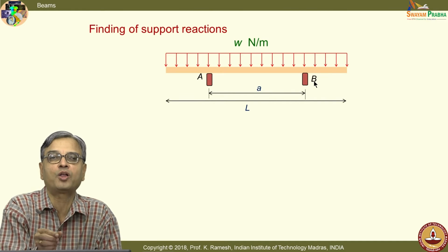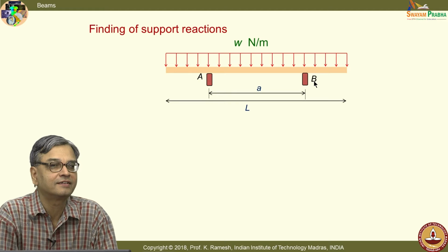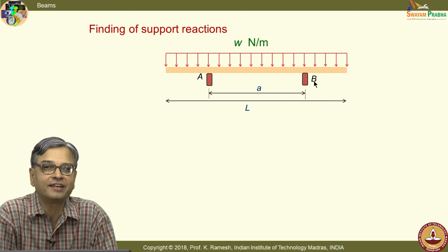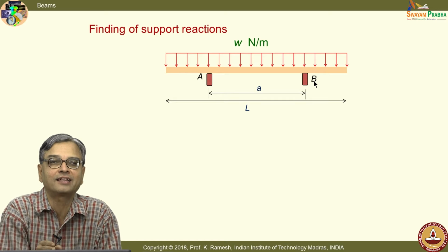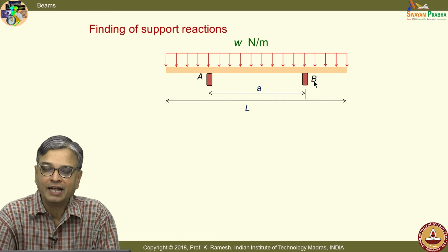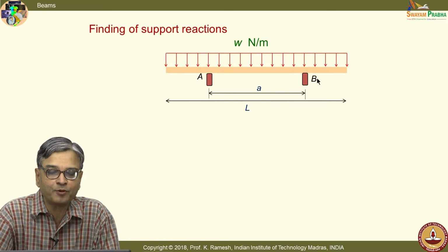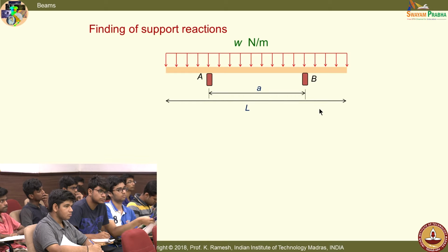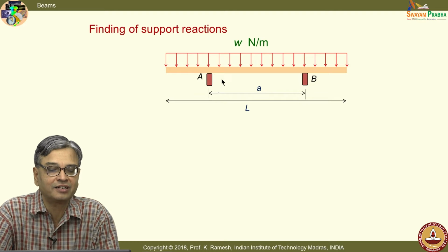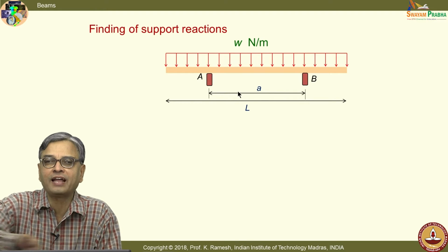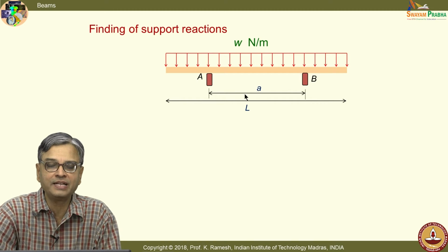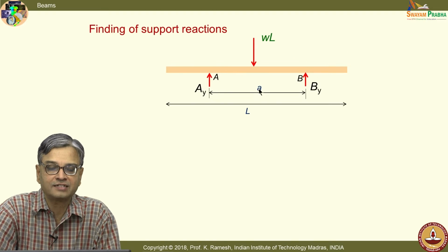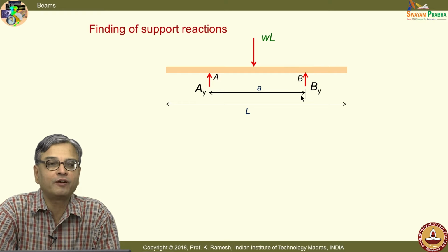You have just taken some blocks and then put them below the plank. Suppose you want to keep your table clean and you have stacks of work, you have found a plank and then put some support. And in what way can I idealize this support? I can simply say it arrests translation in the vertical direction. You can freely move the plank on top of it. So, I can simply say that this is replaced by a normal force.